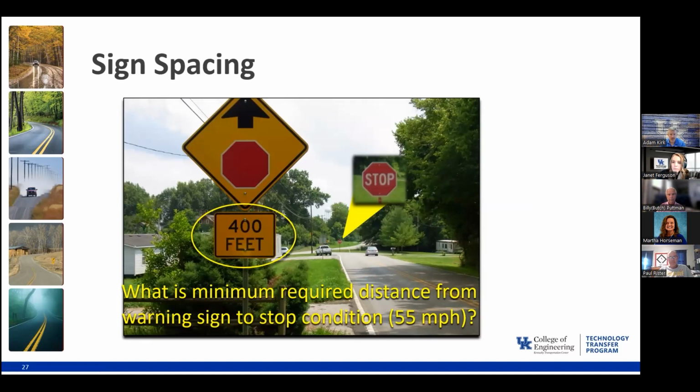So still pretty reasonable, plus, let's say plus 100 feet or so is pretty reasonable in how far we can start pulling that up. And then you can also see that they actually double posted these signs. So this is on the left side of the road, but there's a matching one on the right side as well. So really increase that visibility as you go through there. It could have been this driveway might have hit that 325, which caused them to pull that sign back through there.